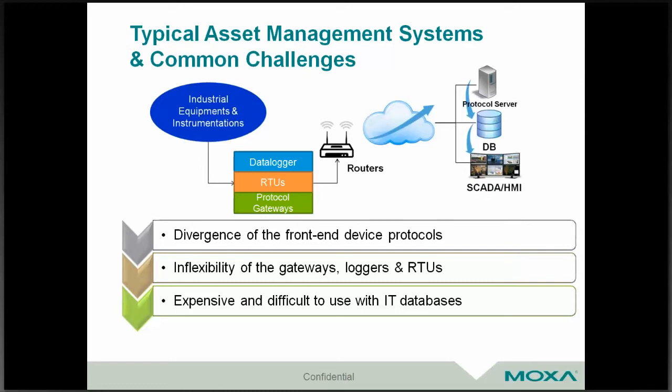How do you overcome that is becoming a problem. The third one is that the IT database is incompatible with the local database where field buses are being used. Converting those protocols sometimes means you have to spend big money on system integrators, or hire software engineers that understand both the database language as well as the field bus language in order to make that conversion. Building up a system like this can be very expensive.